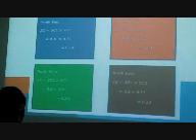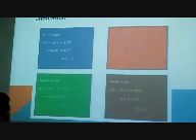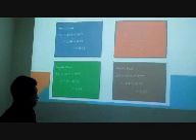This is the calculation to find the shading coefficient, which equals SC1 times SC2. For the southeast, we got 0.23, southwest 0.24, northwest 0.24, and for the northeast 0.23.